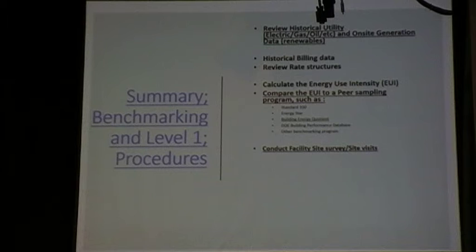Then you have to make a site survey. You have to walk around the building, see what's going on, see where the equipment is, see what that equipment serves, right? Conference rooms, auditoriums, offices, etc., and make a list of that so we can look at it. And then we make a space function analysis. We have to go to each space, or each significant space, and write it down, say what it does, and say what HVAC and other systems serve that.